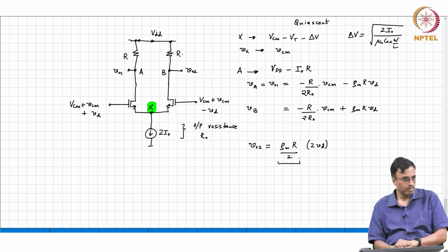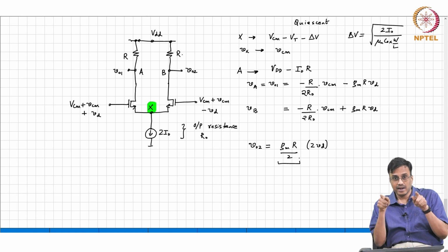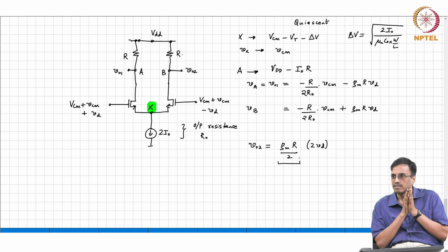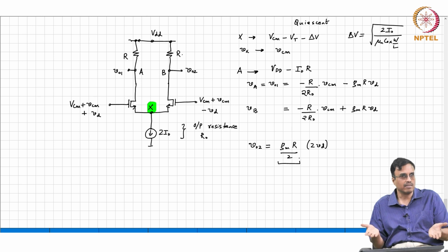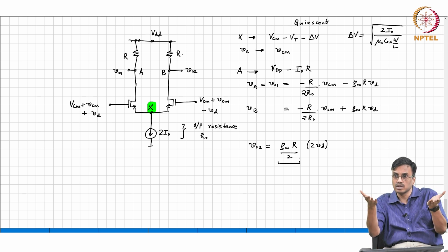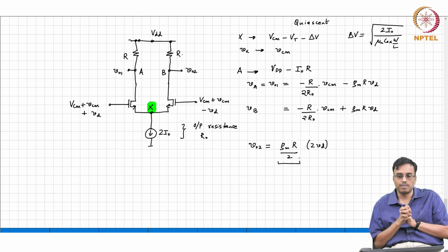Okay. So, this is basically doing the job of a common source amplifier, except that it is attempting to only amplify the difference between Vx and Vy without ideally reacting to the common mode component. In other words, if Vx and Vy change by the same amount, ideally the differential pair output is not supposed to react to the change. However, in practice there will be a small change due to the common mode component, right.